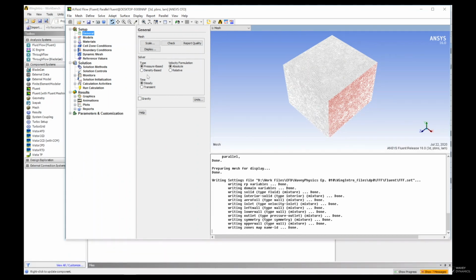It doesn't take into account transient flow phenomena or time-based things like vortex shedding. So you can lose quite a lot of detail, and you also can't produce an animation, which you might want to do at some point. The steady state simulation is a lot easier computationally, and the transient simulations can take quite a lot of time to get you to a decent accuracy. But for today, we'll start at steady.